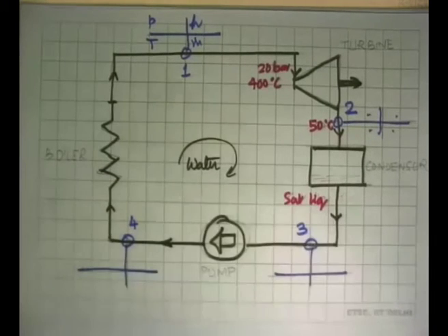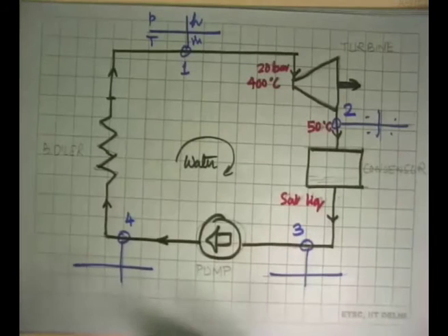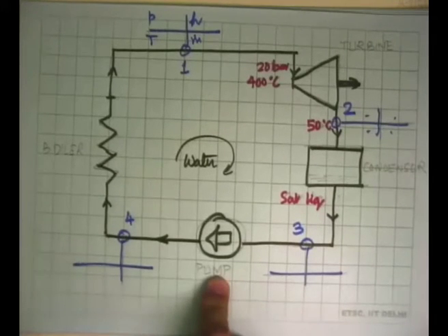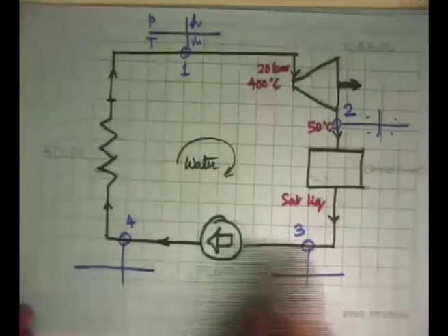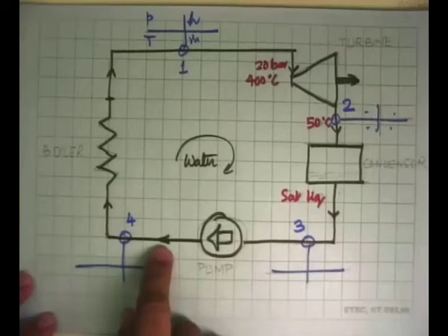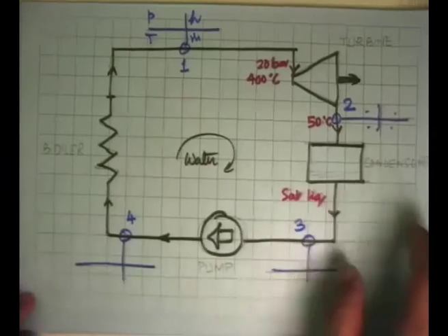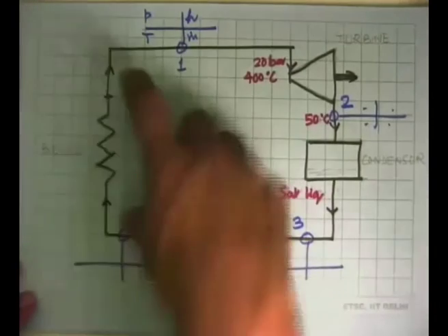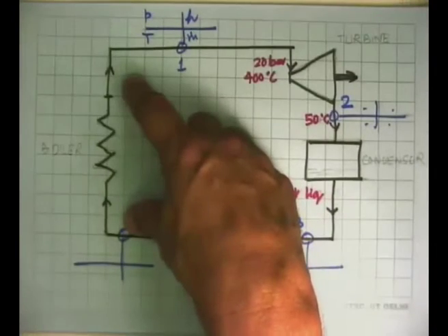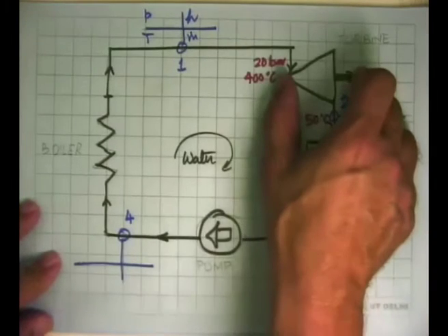This very important information, which is the starting point of design of such systems, contains all the information that we require to say, for instance, buy a pump. We say that I need so much mass flow rate, I'll give some margin on it, I need this as the inlet pressure, this as the outlet pressure, which are the pumps that I should buy. This will tell us the flow rate and the inlet and outlet conditions, which is the boiler that one should buy. Same thing with the condenser, same thing with the turbine.